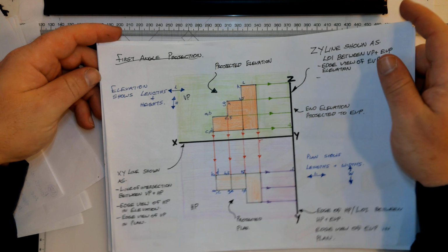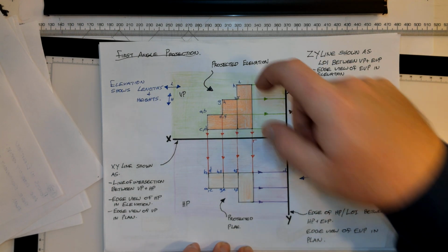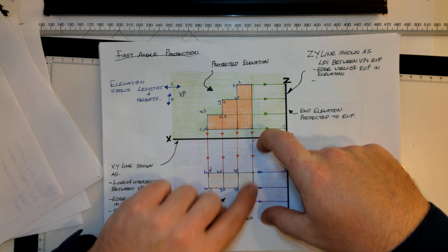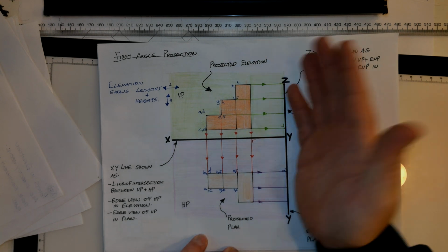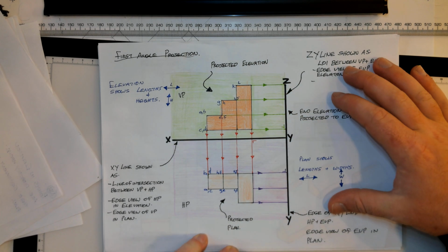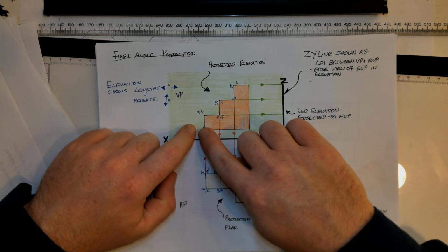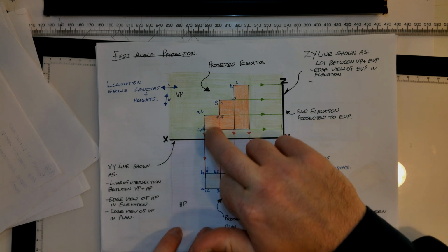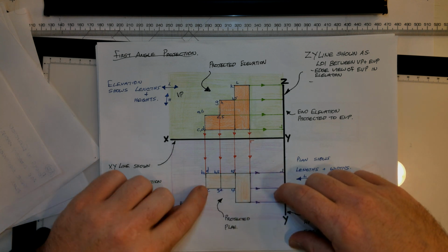Moving on to the next sketch, this is what it would look like now on our page. If we looked in, we would see our vertical plane as we did before. We would now see our horizontal plane, and we would see the plan shown. We still cannot see our end vertical plane because it's not rotated out just yet. So we see the elevation. It shows us our lengths this way and our heights this way. We can see that the points are being projected perpendicular to our XY line, and they come down, and then they show where they are here.